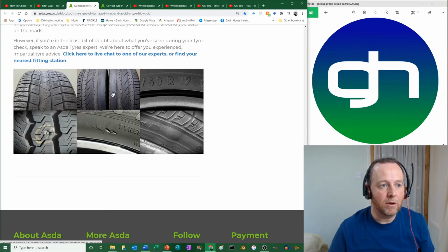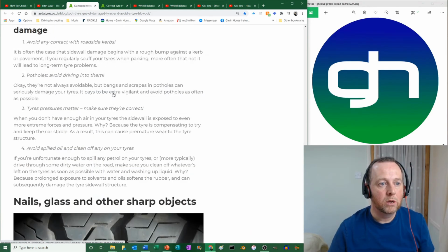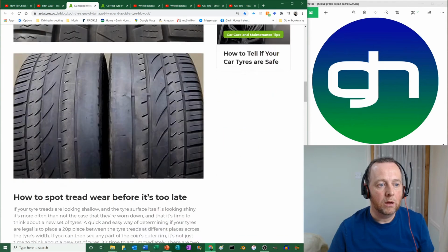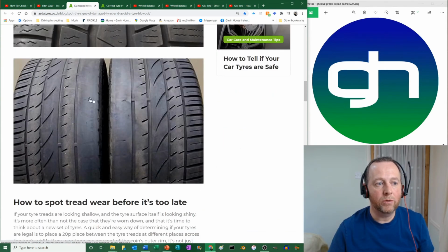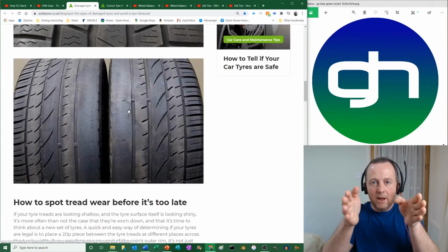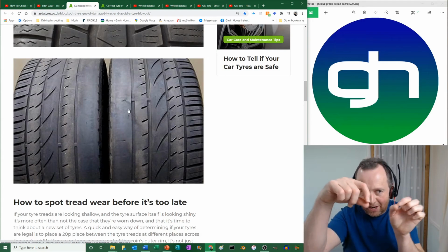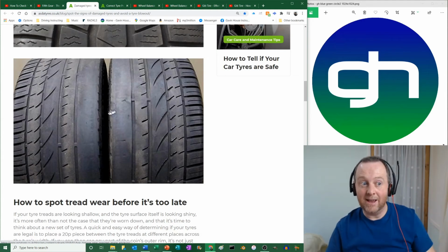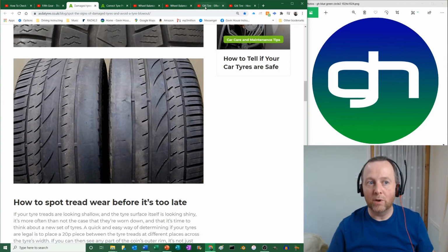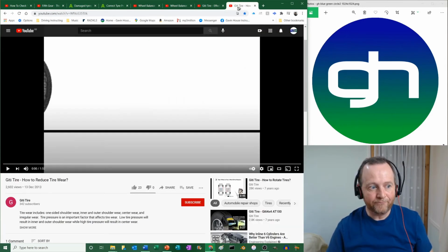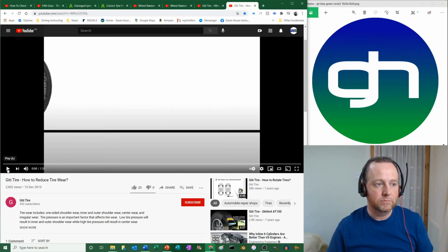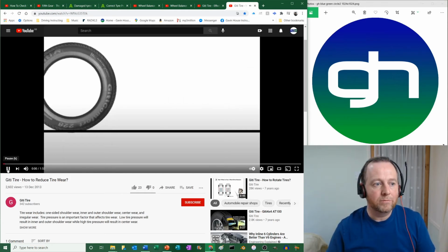If you look over here, look, here we go, look, these walls are bald on the insides, and that's where the alignment's out, but we're steering to the side, so we're actually just using the inside edges of the tyres. So that is an example of wheel alignment that they were talking about. And then finally, how to reduce tyre wear. You've got the idea by now, I hope.